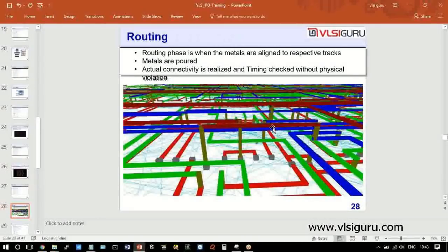From one metal layer to another metal layer is called a via, and from substrate to the first metal is called a contact. Via in English means via, go through. That is what a via is. I remember my physics teacher in school days; everything he used to give an analogy. As kids, if you have an analogy, then we usually don't forget. So similarly, I won't go into big analogies or phrases, but I will tell it's just an English meaning, very simple. Via, it just goes through. Contact is not a via. It is contacting your transistor. That is why it's called a contact.